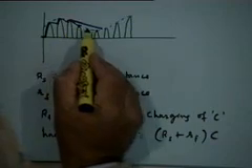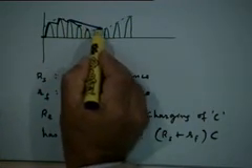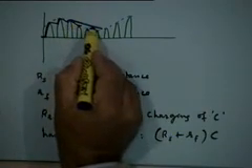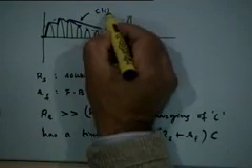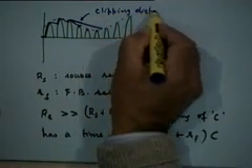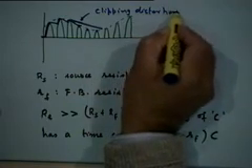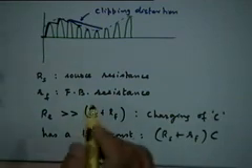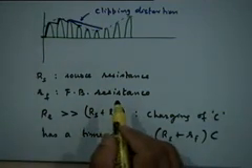This envelope fluctuation here is much faster than the rate of discharge of the capacitor, and therefore there is a kind of distortion that will come up in the envelope which we call the clipping distortion, right, and which we should avoid if we want to get a faithful reproduction of the envelope, right?